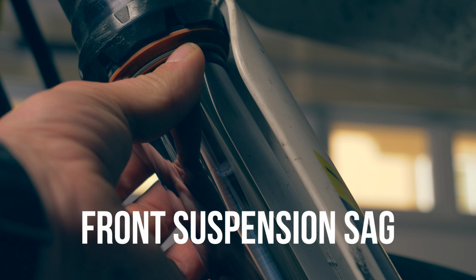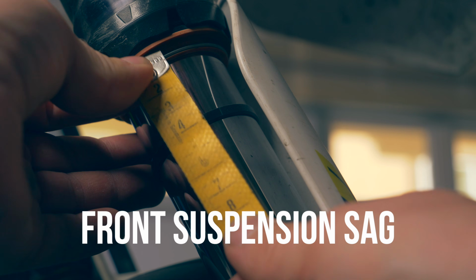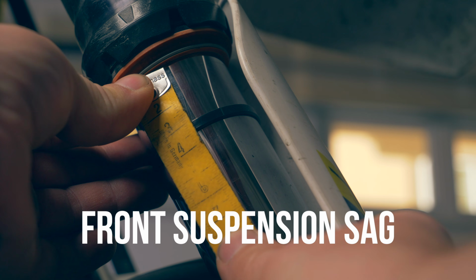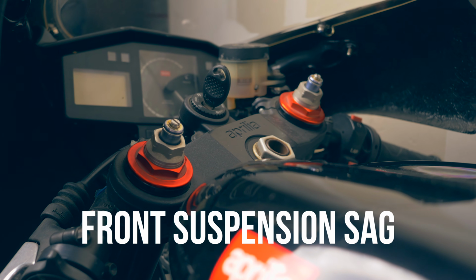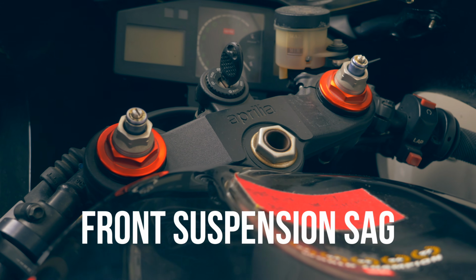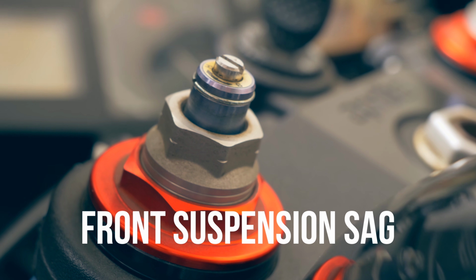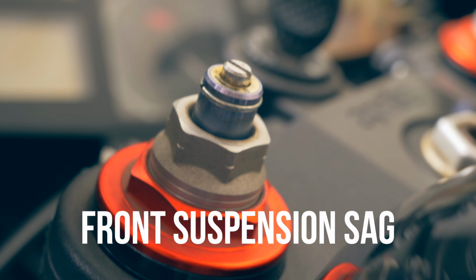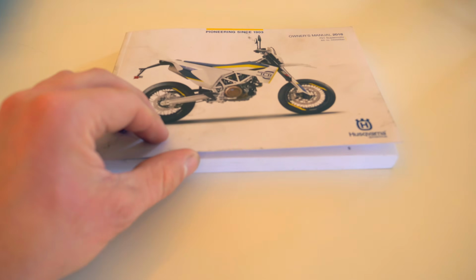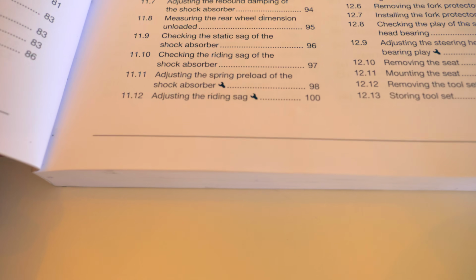Have your mate push the zip tie to the dust seal. Now get off the bike and pull the bike up so that the front suspension fully extends. Have your mate measure the distance between the zip tie and dust seal. That is your sag. On most motorcycles, you adjust the front fork preload with a wrench. They typically move independently of the fork tube, looking like this. More lines equals less preload. Fewer lines equals more preload. Please see your owner's manual on how to do this on your specific motorcycle.